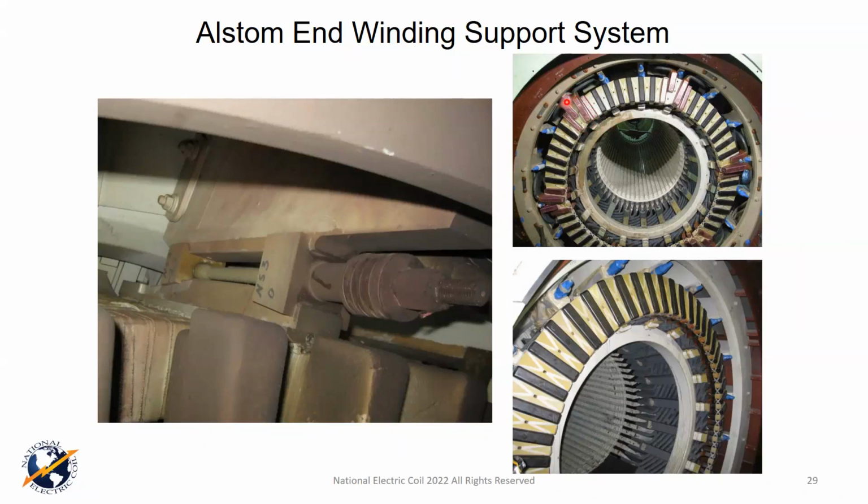I believe Alstom and many of the OEMs to be quite competent, and I believe they qualified their brazers and folks just like we do, and we put them through the reins and usually requalifying before the jobs. But that doesn't mean that you can't have a cold braze. But there are testing methods you can use to help pick those up. And by qualifying your people, there's a lot less chance of having braze problems. But you also need to be careful of what the procedure is overall. Is it a good procedure? With good trained people, will it yield consistent results consistently? Okay. And those are some things I would have to say about that.